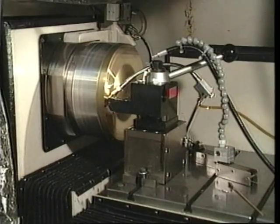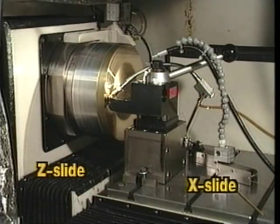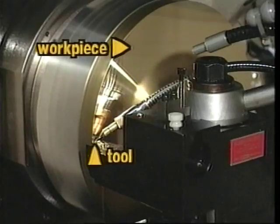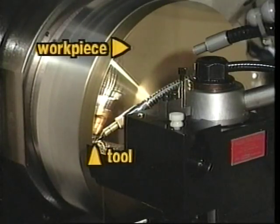The objective of this lab is to demonstrate squareness of motion measurements. Specifically, we will measure the angle between the two axes of motion on this ultra-precision lathe or diamond turning machine. In this diamond turning machine, or DTM, the hydrostatic bearing slides or carriages are configured in a T-shape. The rotating spindle and workpiece ride on the Z-axis slide, while the diamond cutting tool rides on the X-axis slide.